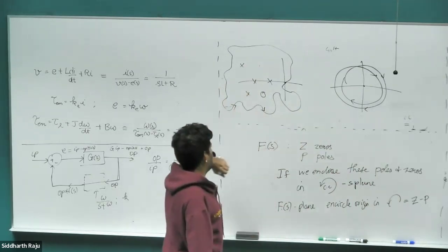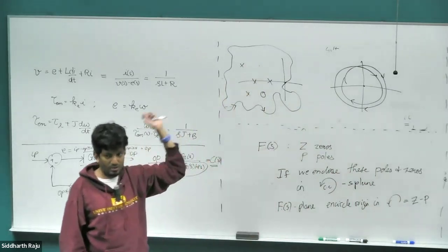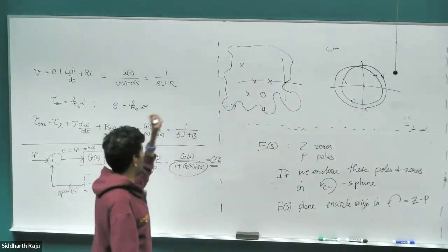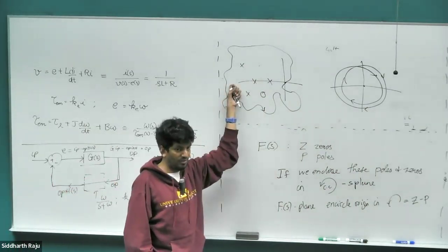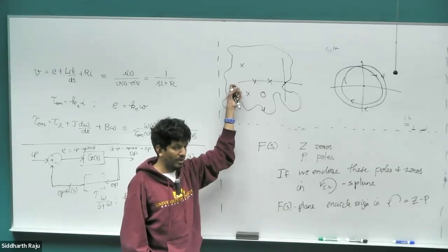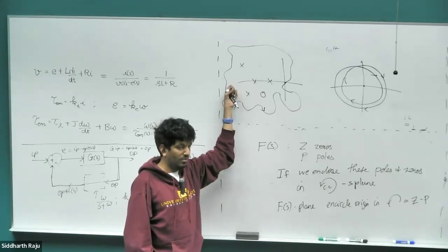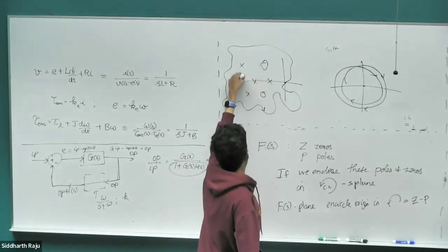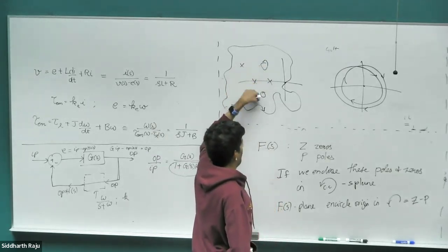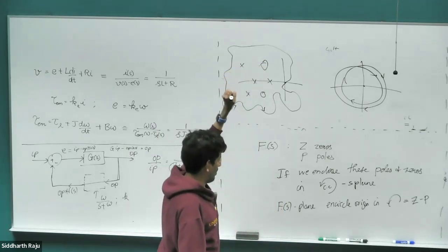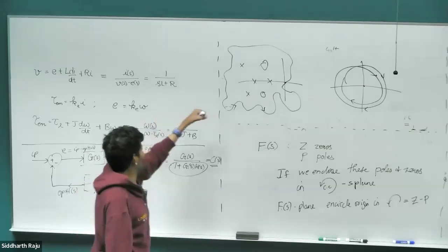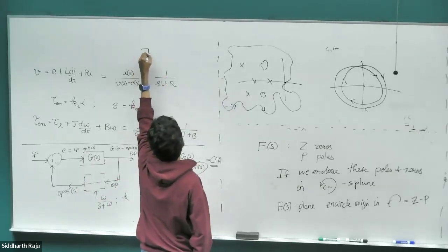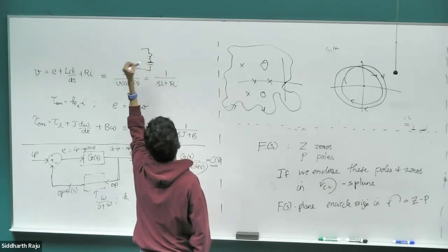Can I have a transfer function that can be modeled using the diagram that I've shown there? Can I get a transfer function with these number of poles and zeros that I've shown there? No? Why not? Has to be symmetric across the x-axis. So whenever I have all of these poles and zeros that are off axis, they would be complex conjugates, right? The reason these poles come out complex conjugate is if you have, let's say, an LC network of some sort, right?